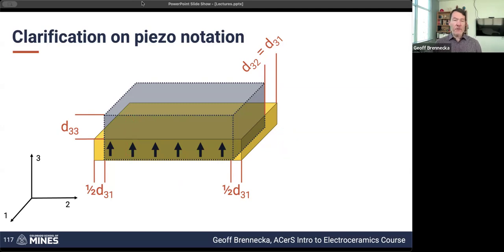So whether we measure the d33 or the d31, when we apply a field along three, we get strain in both three and one. That's what these coefficients are referring to. And the way that I drew it on here, I basically fixed the bottom and had the entire strain sort of growing up from that. But then I also wanted to show that you're getting lateral in both directions. And in the two direction back here, I just showed it as one. So hopefully that doesn't confuse people, but I wanted to clarify what the three and the one and two and all these mean for starting off with a completely random material.